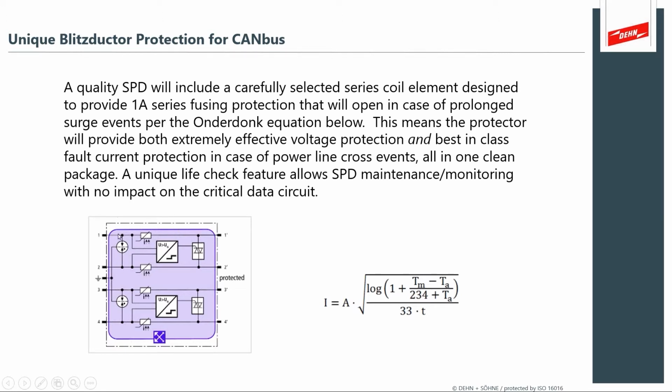And then we see what is essentially a series element that offers a fusing type process. So in one device, we have the surge protection and fusing for surge current control. And then on the protected side, we're showing what looks like a high powered Zener voltage control device to offer the best protection at the protected side of this type of equipment. And we use this type of SPD device throughout the next several slides where we're discussing applications in detail.